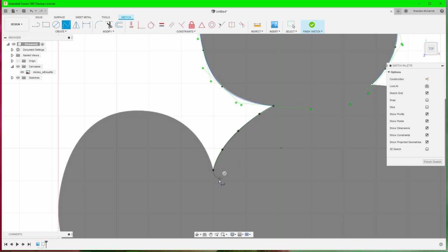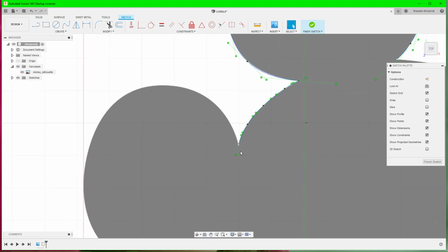Now, before I continue here, earlier we held down the right button until this menu popped up, right? Well, you don't have to wait for that menu to pop up. You can just click and drag. And you see that little blue line? It automatically will select OK. Shift S to open up my fit point spline again. Continue around Mickey's head, or his ear rather.